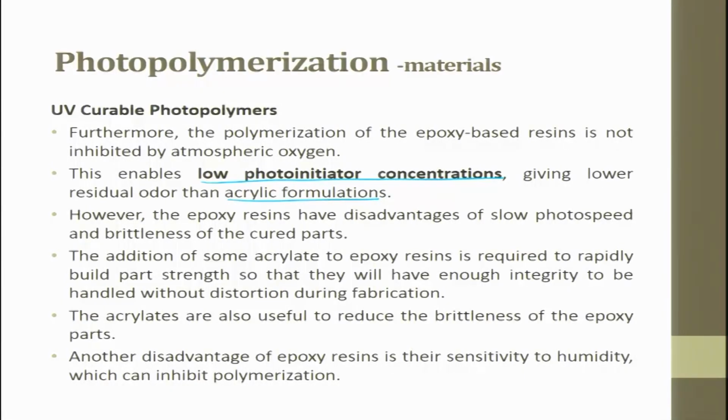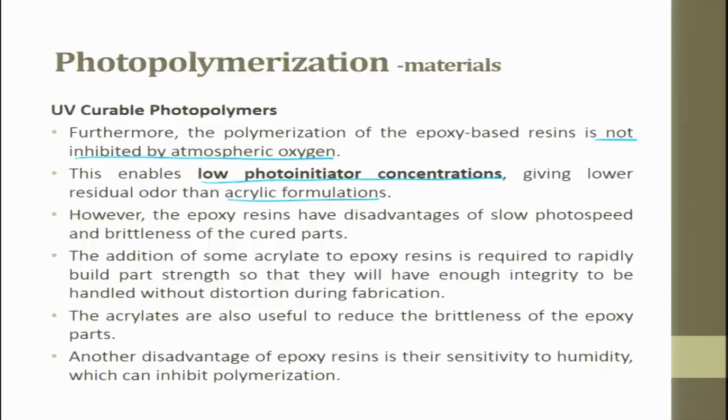Okay. So, this is not inhibited by atmospheric oxygen. Acrylic reacts with the atmosphere, but epoxy does not react with atmospheric oxygen. This enabled low photoinitiator concentrations, giving lower residual odor than acrylic formulations. However, the epoxy resins have disadvantages of slow photo speeds and brittleness of the cured part because it is thermoset. So, it will have brittleness of the cured part.